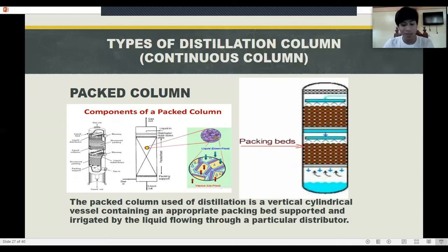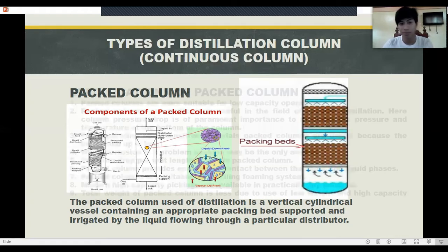For standard mass transfer operations, packing can be considered as an alternative to conventional trays. However, packing is more sensitive to fouling problems than trays, and special attention to distributors at the design step is required. Packing could be a good solution for revamping units where extra capacity, energy savings, or higher purity products are required.